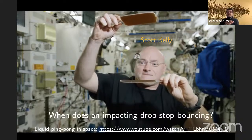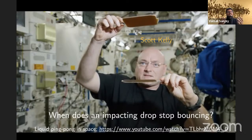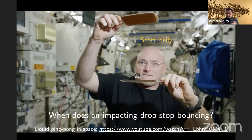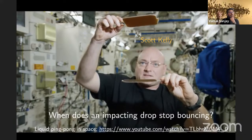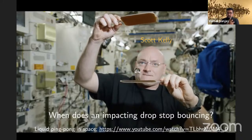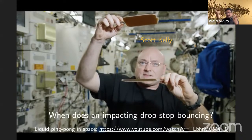No, I don't think there is any experimental observation there. Irrespective of the size of the droplet, the drop will have a Bond number of 0 or very close to 0, because g is effectively 0. What would happen is that since we are going to bigger droplets, the Ohnesorge number will be very small, even smaller than 0.001 that I showed you in the previous slides.